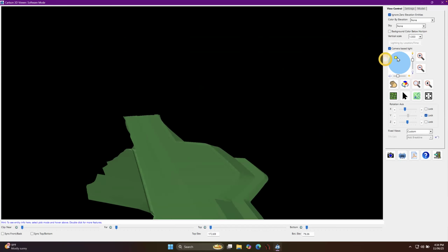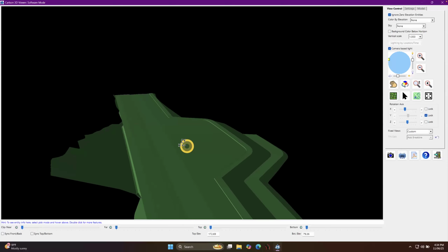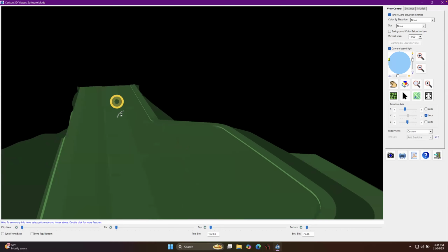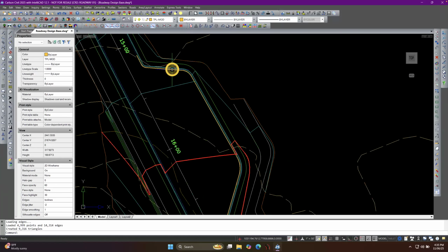Now, one of the things, let's see if I can get a shadow to show up here. If you can tell from this, it went from here's the crown of the road, and it goes down, curb, and comes up, sidewalk over. And so that pushed that out there, and it kept that at that same slope. It just went from what used to be the edge of pavement here and just pushed that on out at that same slope. That's when you only use the center line, the template point center line.